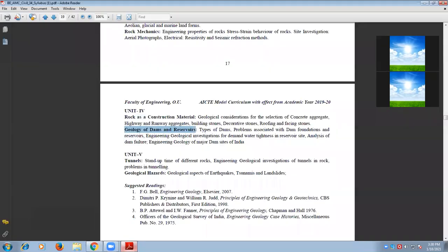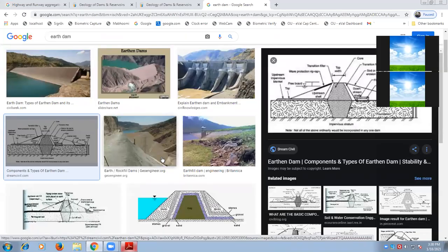Dam disasters or dam failures occur due to miscellaneous reasons. Some of the disasters are caused, for example, by dams on shales. There are two types of shales. Shales are rocks actually, and they are cementation shales or compaction shales. During construction, generally the cementation shales are stronger, but they are soft and soluble when subjected to wetting and drying. During excavation work, swelling may develop and create more problems. Therefore we need to coat the surface of the rocks with asphalt, and gravity dams will not be constructed on compaction shales.